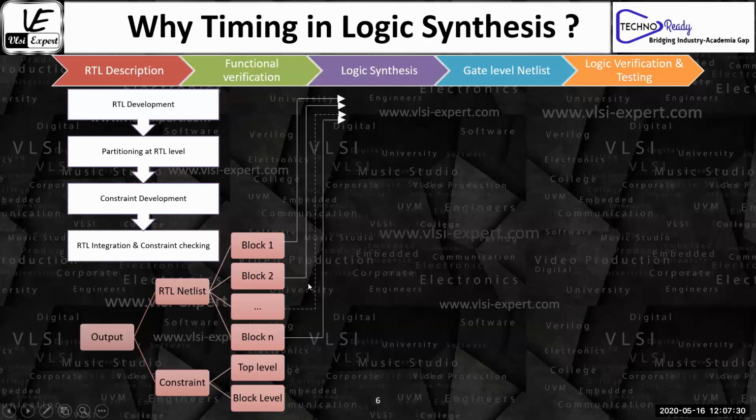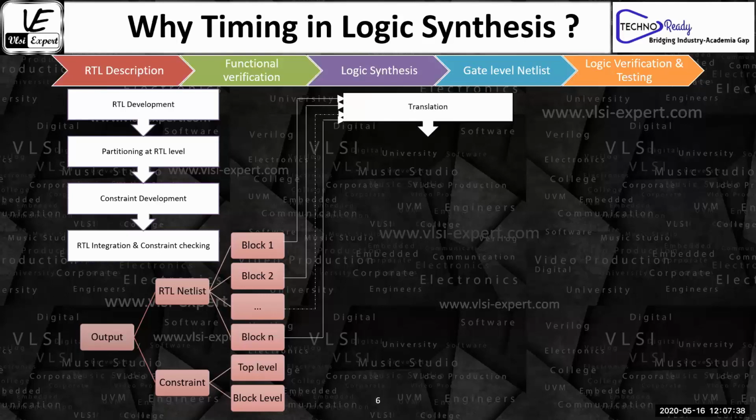Now let's talk about what logical synthesis is and what is going to happen in logical synthesis. So now you have the RTL of all the blocks. The RTL is just in a language. In the language you have mentioned, okay, A dot B. That means it is an AND gate. It looks like an AND gate, but how you're going to design it logically is a part of logical synthesis.